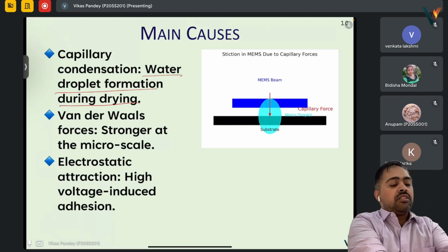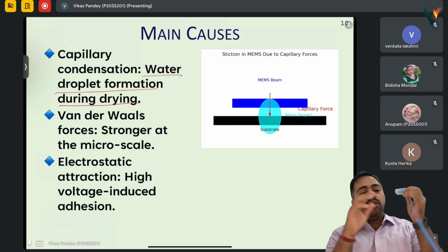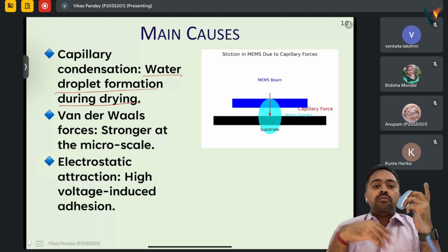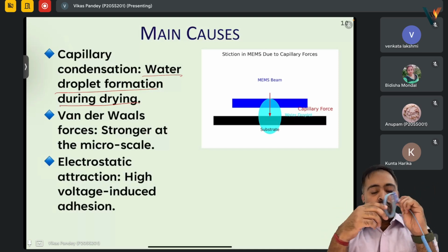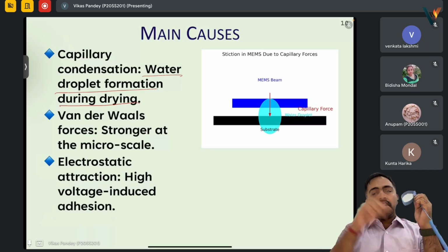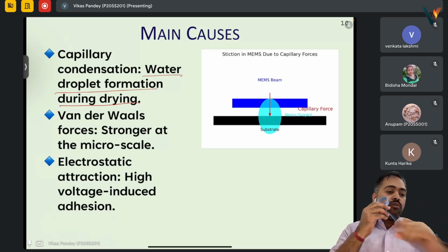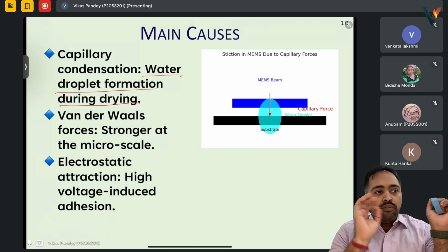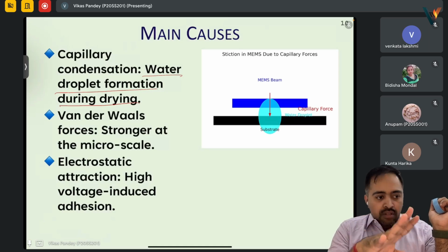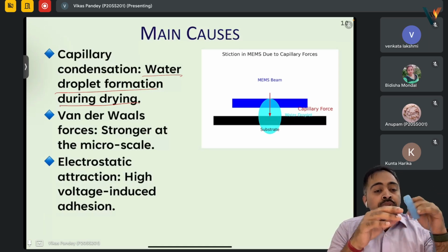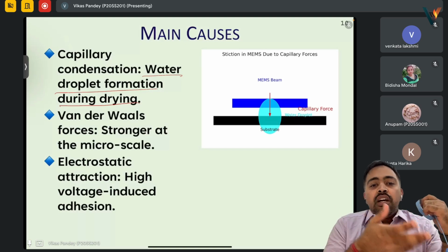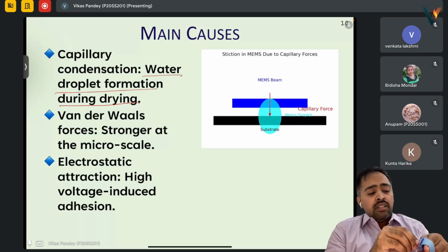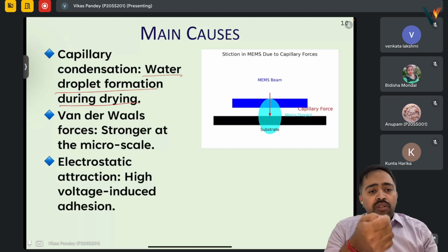So you see, such straps are used when working with these structures. These are conductive straps, so whatever charge is in our body will be conducted, and these are connected to the ground. It has wires, and it will be connected to a proper, very good earthing and grounding system, so that no charge is there when we are handling these materials, even with tweezers.